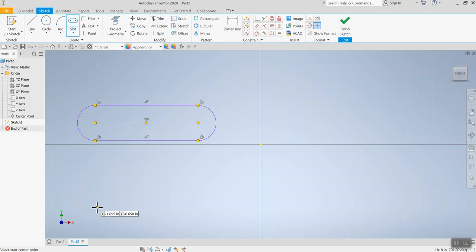Again I am doing it one more time. I click the first center, then I can make it horizontal or whatever angulation I want for the second point. Once I select the second point, it will all be frozen. Then I can take the diameter of the arc, or of the slot, or the radius. This is the first kind of slot, which we call center to center.